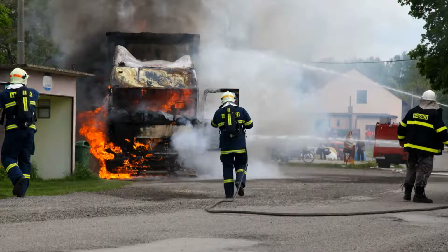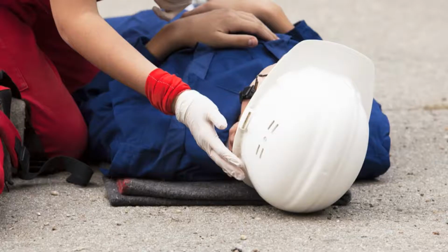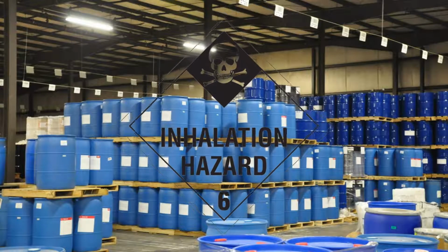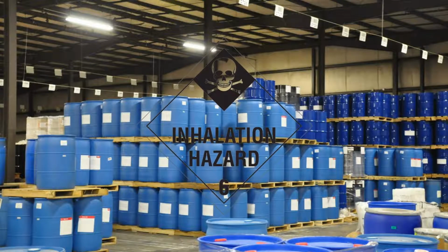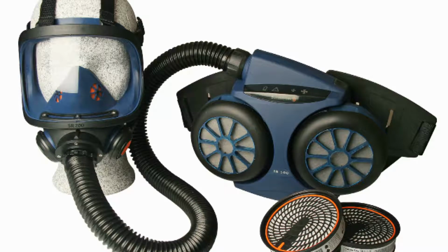If a chemical is inhalable and workers are exposed to it, they have no choice, as they cannot stop breathing and cannot prevent inhaling. Therefore exposure to inhalable chemicals is very serious, and any worker exposed to such chemicals may get severe health effects by inhalation. Working with inhalable chemicals needs extreme care in carrying out the risk assessment, and more care must be taken in the selection of PPE.